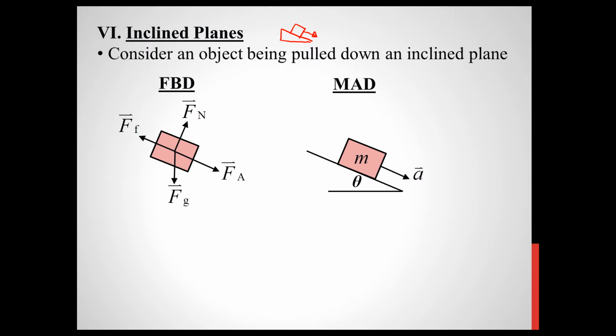So of the 5 vectors I can see from the free body and mass acceleration diagram, if we took our standard approach of dealing with the horizontal and vertical planes, we'd have to break 4 of those 5 vectors into x and y components. That would make it a nightmare to deal with the equations of motion. So what we don't want is to use equations of motion that are in the horizontal and vertical plane.